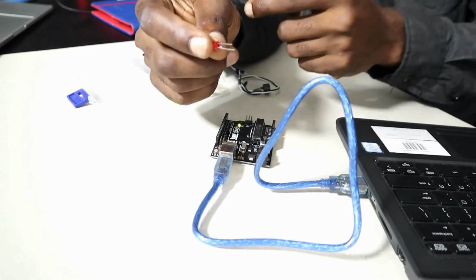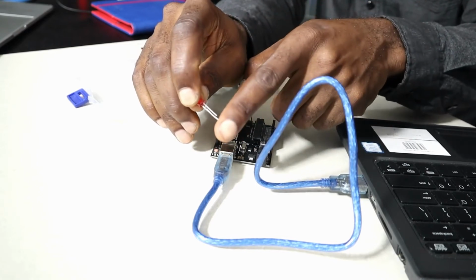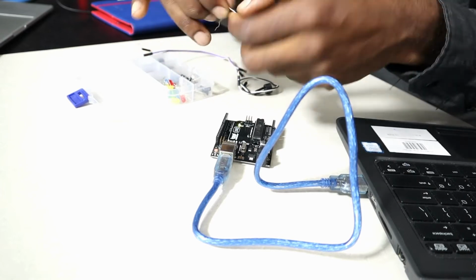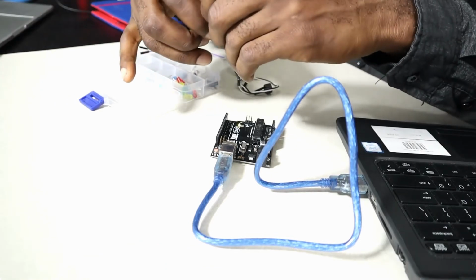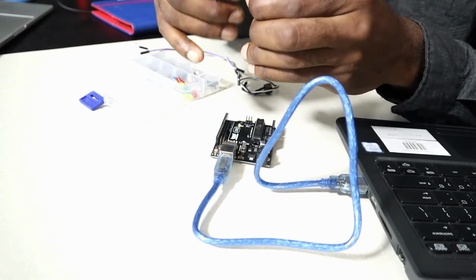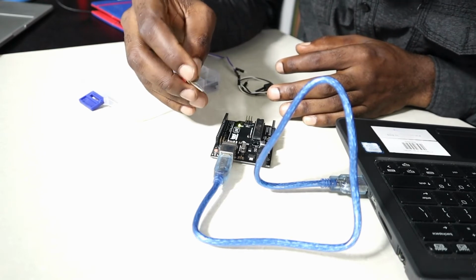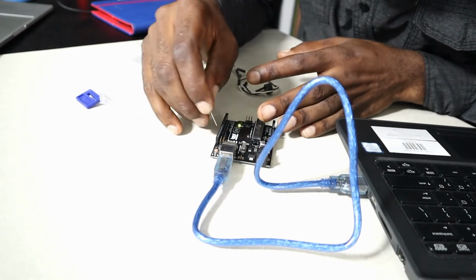Remember that the longer leg of this LED is the positive, while the shorter one is the ground. So the longer leg is the positive. So I will just twist a resistor. You have to be very careful because we are tapping directly from the board, so that you will not flash the controller. So check ground. I have a ground pin. Put my ground pin.